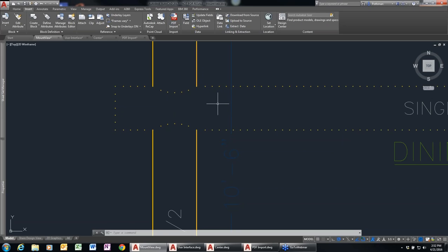But there's a new setting in AutoCAD called LT Gap Selection. Again, you don't have to type in the whole thing. Just start typing it, and then I can pick it from the list here and get it. And I'm going to turn that on. And now what I'm going to do is I'm going to go and move my cursor again, and hopefully you can see this. And I'm not going to pick on the dot, but I'm just picking in between the polyline, in between the dots, and it still allows you to select the polyline. So you don't have to have something that intersects.